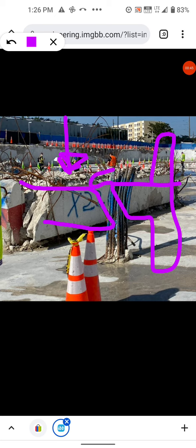And this right here is where you get the little shear break, they call it. I say they call it because I think it's really a tension break and not a shear break. I think the tension is created in there so great that you get this. I'm biased. I am thinking shear on the lines of only scissors crossing each other, a punching into something. It shears around the outside walls of it, and that gets you your shearing action. That's the punch that you call it, but in reality, shear took place also.